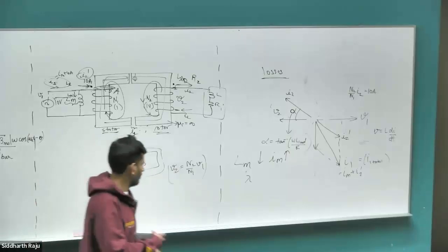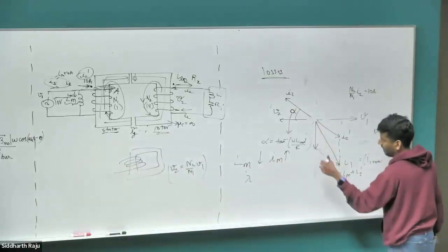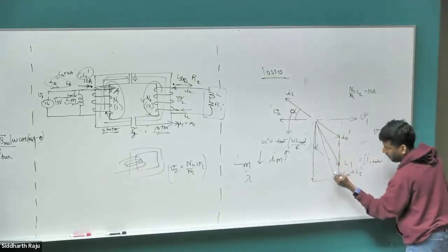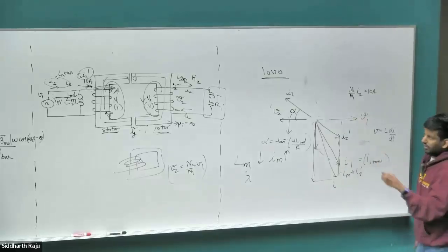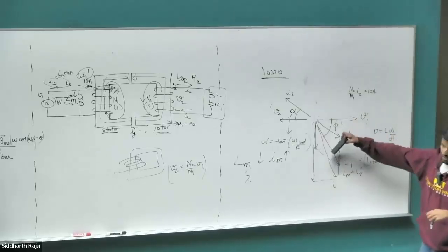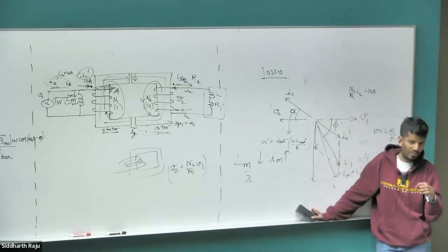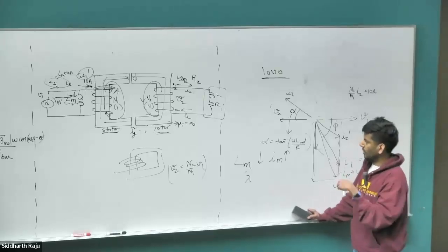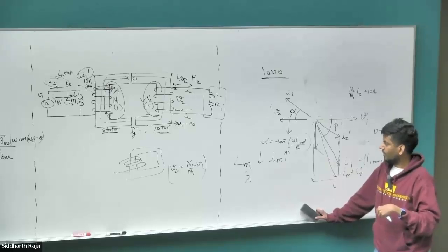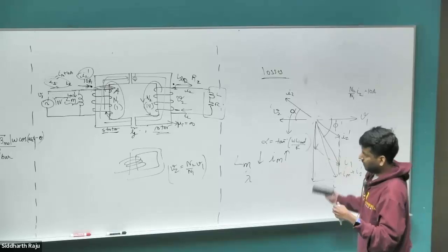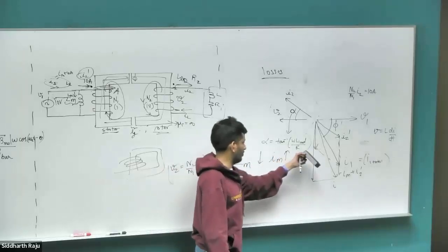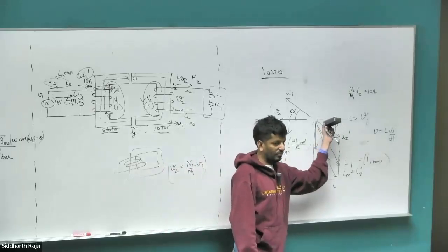Power factor? Power factor. So as this vector IM keeps becoming larger and larger, the net current moves farther and farther from your voltage, V1. Right? And the angle between the voltage and the net current is your power factor angle phi. So as that angle increases further and further, you're consuming more and more reactive power, which has its own problem, and the grid operator would put a penalty on you if you take quite a bit of reactive power. Right? So for every kVAR that you consume, the grid operator is going to put a huge penalty on you. So you would have to have some kind of compensation mechanism, put some capacitors or something, so that the reactive power can come back, which has its own expenses. Okay?